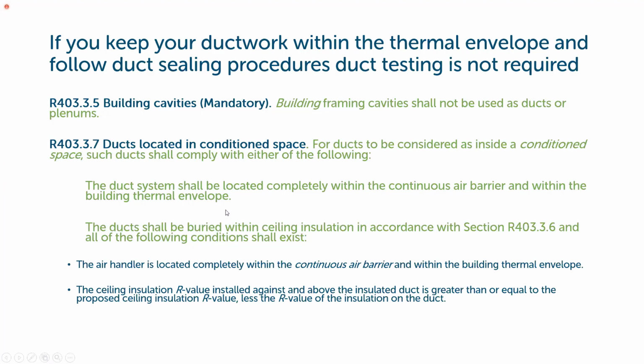And any ducts that are within that thermal envelope itself, they need to be buried with insulation in accordance with R403.8, which covers what those insulation requirements are. It's the next slide.